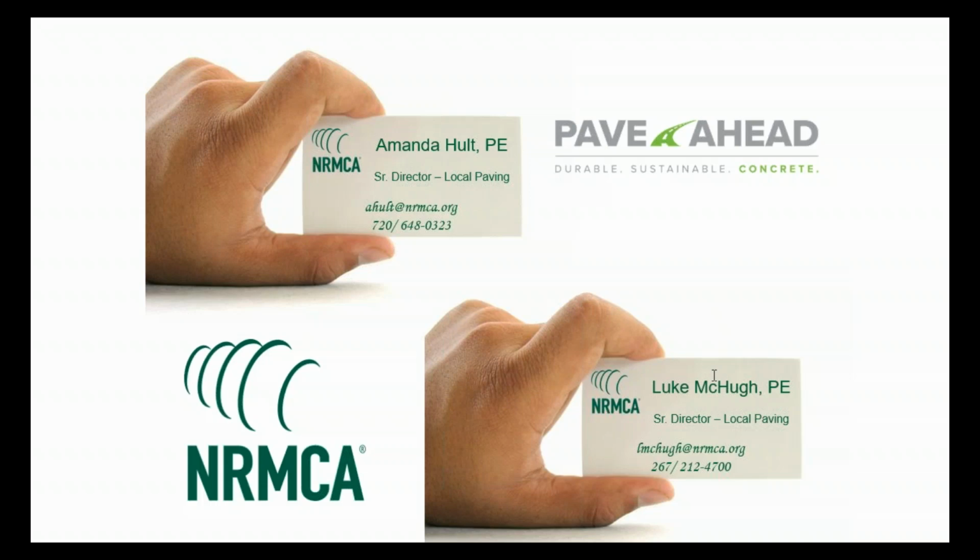All right, it says, is it possible to dictate the desired jointing and get a revised thickness? In this particular software that we have, pavementdesigner.org, it does not allow us to do that. The design is pretty straightforward as far as the inputs producing a thickness, and then it will calculate the joint spacings based on that thickness. It does not allow us to manipulate the joint spacing.